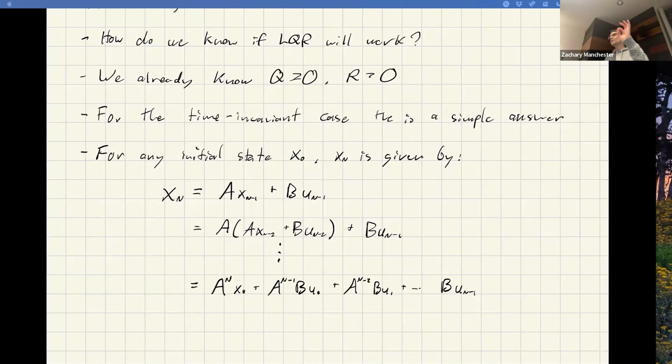So I'm propagating these things through. And yeah, the ill conditioning comes in. Say my system's controllable, right? All good. I can always do what I want to it. But let's say it's open loop unstable. What I mean by open loop unstable is, think about an inverted pendulum. Perfectly stabilizable if I have control, but the A matrix is unstable. So in discrete time, what does an unstable A matrix mean?